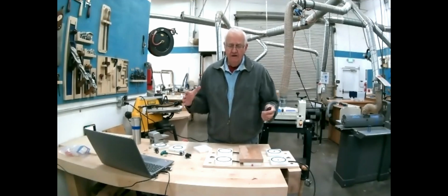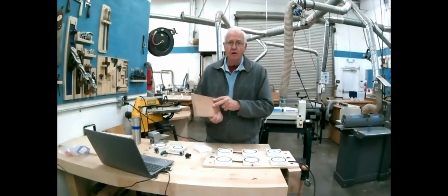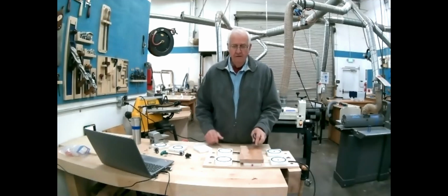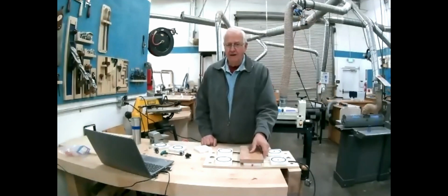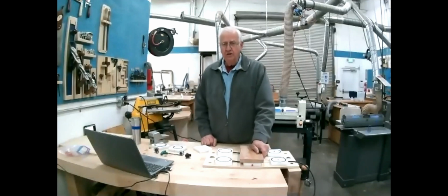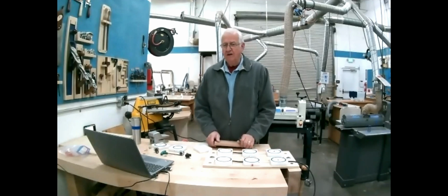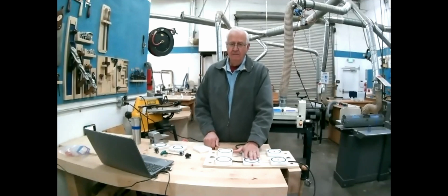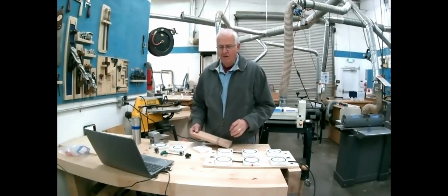If I have a piece of cherry, some closed grain wood, and put it on here, my pump will only come on every couple seconds, maybe for 2 or 3 seconds, maybe once every 2-3 minutes. There's that little leakage going on there. But if I put a piece of MDF on there that's say 1/2 inch, no finish on it, it's going to cycle maybe every 20-30 seconds. There's just that much leakage in an open material. Or if I had white oak, it was thin. Got it. Okay, thank you.